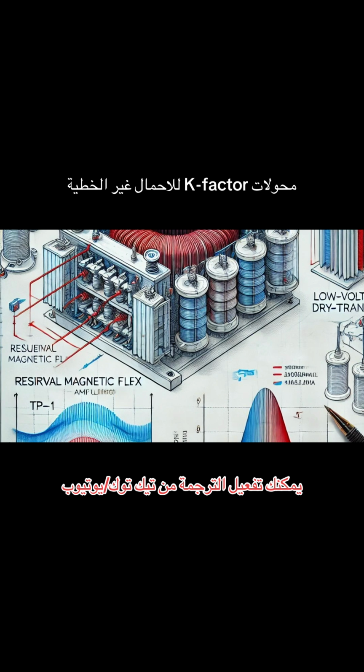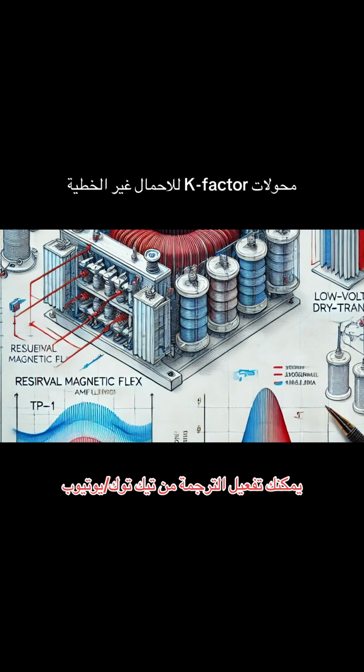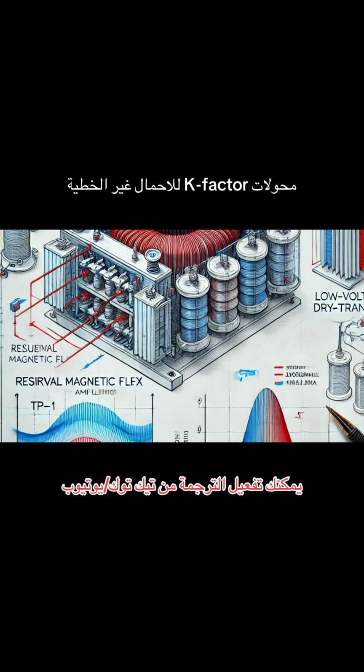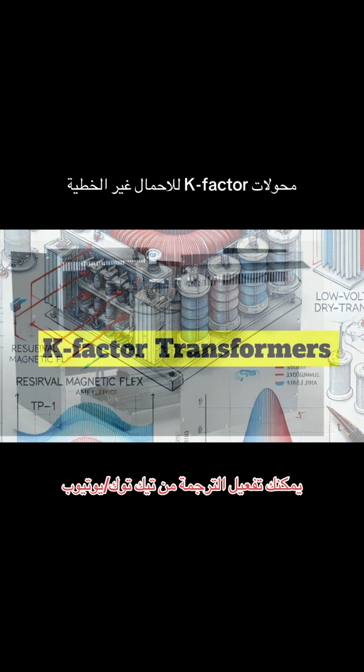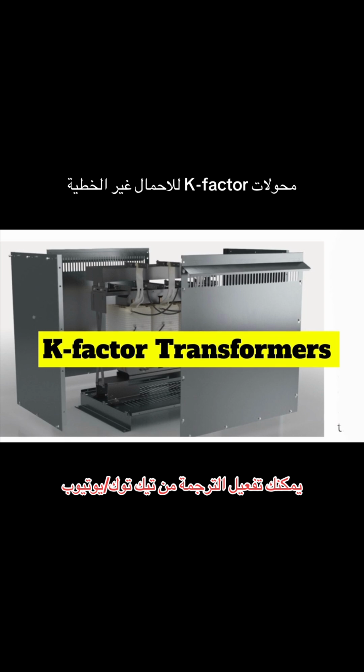The other interesting point the paper brings up is about the efficiency data that manufacturers publish for these transformers. Okay, what about it? Well, because of energy efficiency regulations, manufacturers usually provide energy loss data for K-rated transformers based on how they perform under ideal conditions, with a perfect 60 Hz sine wave, no harmonics. This is done so they can be compared to other transformers in terms of energy efficiency. I see. So the efficiency numbers you see in the specs might not reflect how the transformer performs in the real world with all those harmonic loads. That's right. It's something to keep in mind.